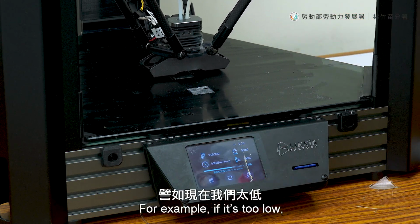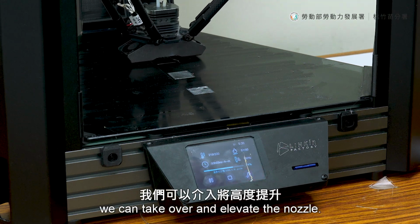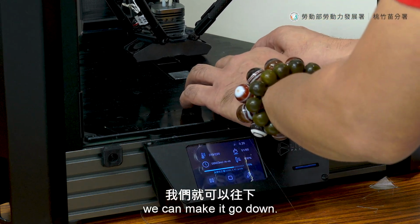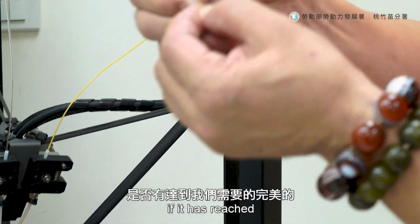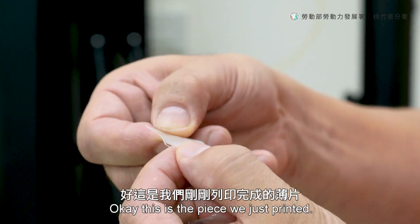For example, if it's too low, we can take over and elevate the nozzle. If it's too high, we can make it go down. After adjusting, we can check the second piece to see if the height is okay, if it has reached the perfect height. Okay, this is the piece we just printed.